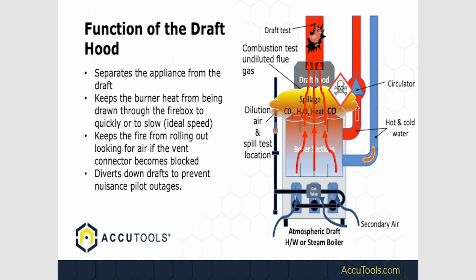The positive pressure is going to flow up in this area, and because there's a negative pressure here, it's just going to pull those flue gases in along with dilution air up that hood, right? So when we have our air come in, there's all the secondary air that comes in. Once you start testing older appliances, you think, oh, these are going to be really, really inefficient. And you look at the excess air readings, you can see they're actually running really, really low excess air, and the excess air is very, very well controlled because these appliances took air in at exactly the same rate that they went out. It's just natural draft drawing that up in there.